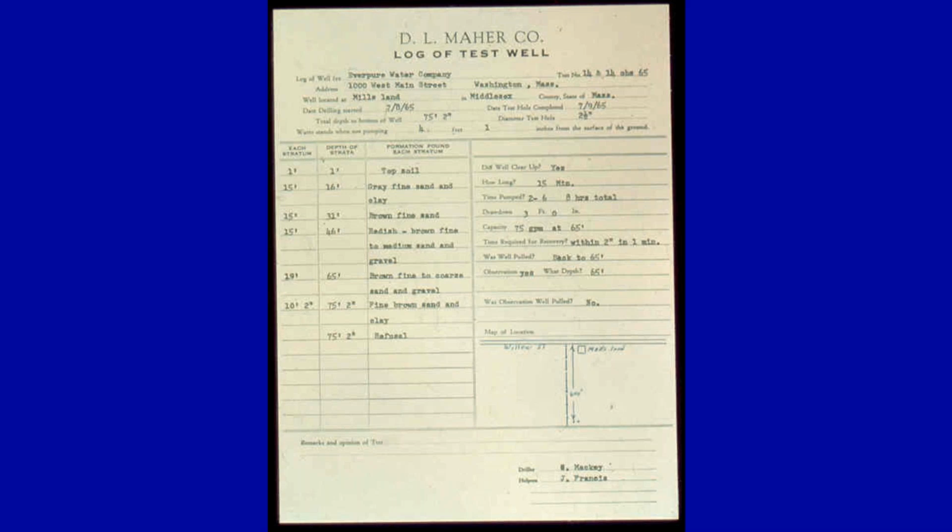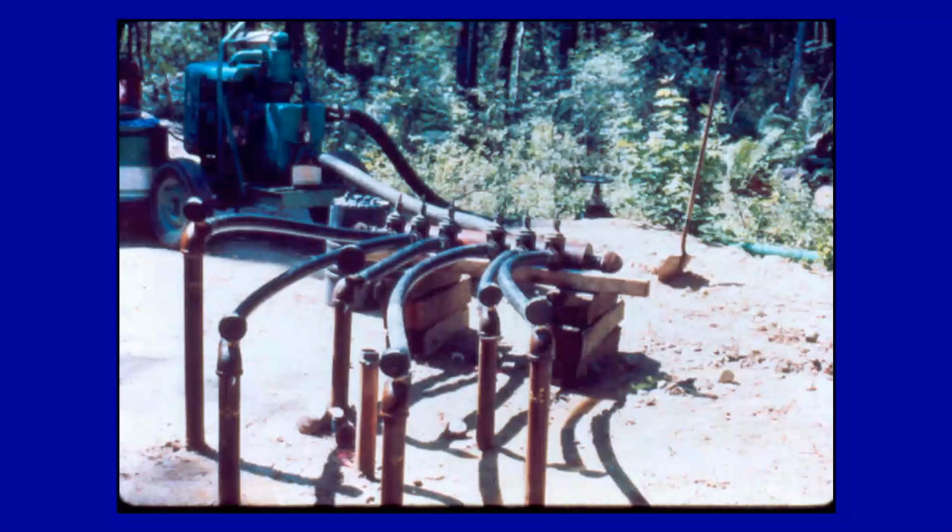We note the color as indicated before, which is important because we may give up some potential yield to develop a shallower stratum, which may in fact have better water chemistry. The duration of the pumping test would be noted, and what the total drawdown in the observation well would be. Also, it should be noted how quickly after the pumping is curtailed it recovers back to the original static water level.